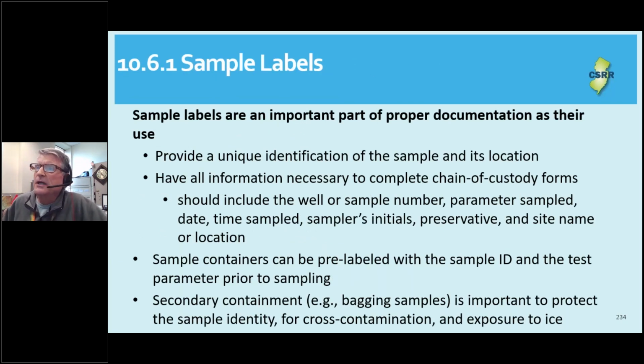It's critical that the field sample number be unique to the sample being collected, because a sample may only be one of a number of samples processed in a batch by the laboratory. This field information is transcribed into the Laboratory Information System, or LIMS, and a unique laboratory number is assigned for its subsequent sample analysis. Sample preservation specifics, method of analysis, and holding times for a specific analytical parameter and method must be specified in the Quality Assurance Project Plan and the sampling plan.